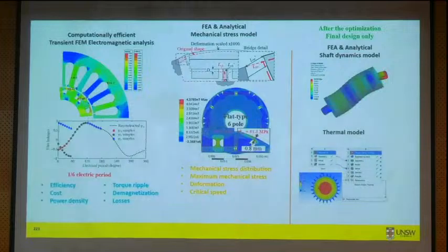And another thing is that, as I said, multiphysics means it could take you a very long time, because you are doing electromagnetics, which already takes time, and then you are also doing mechanical, or you may do thermal. So you want to simplify things or reduce computational time.